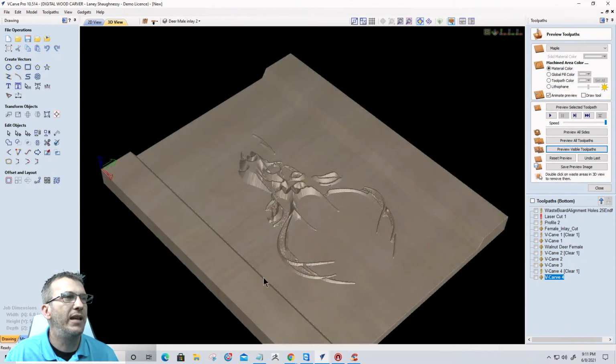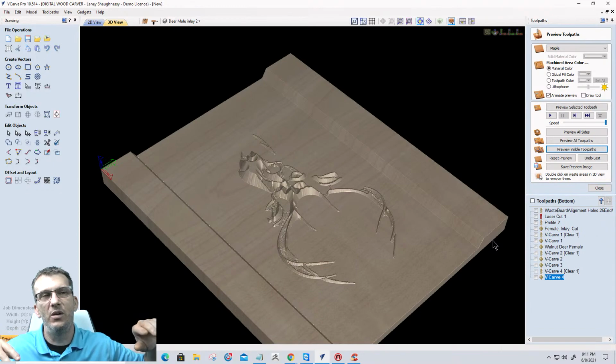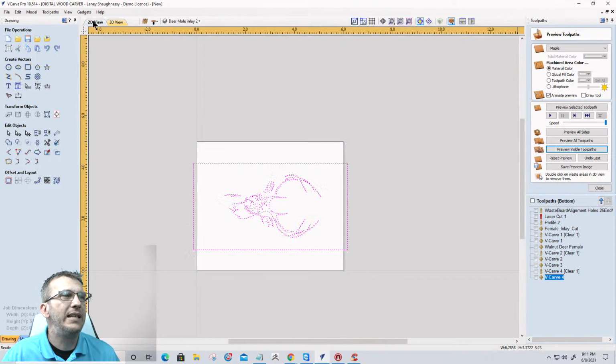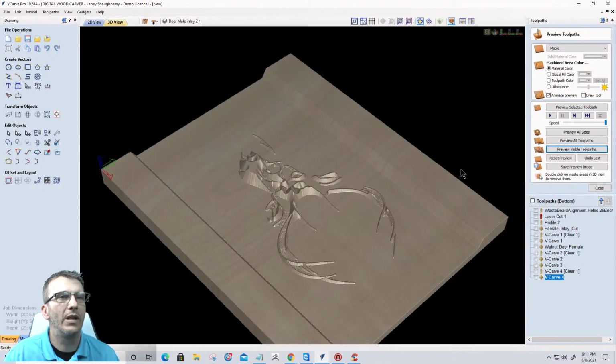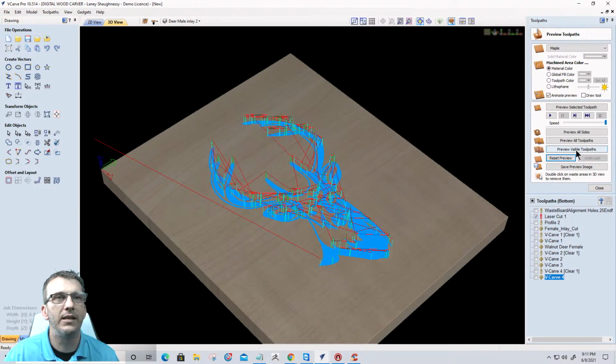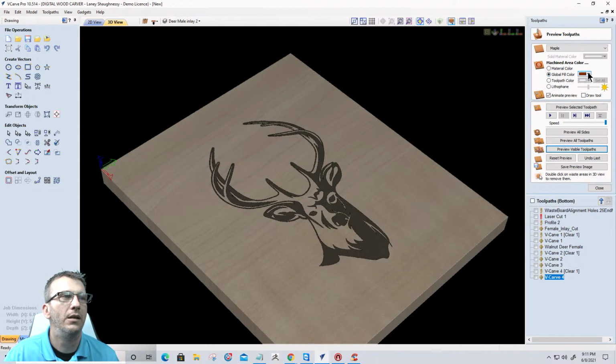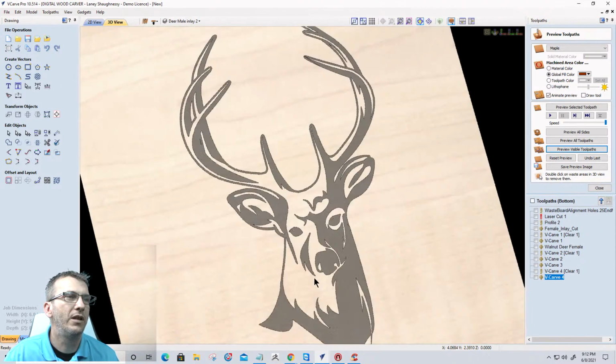So we would come in and mill off the side edges there, run it through a bandsaw, handsaw, whatever. Take and glue this into that female cut, and then when it's all dried, give it a few hours, overnight, whatever, to really cure with a lot of good clamping pressure. Clamping pressure is important, and then mill that off. And now, basically, what we should have is, if we were to look at this again, this time I'll do it with a global fill color here. It's not going to give me a global fill color on a laser.